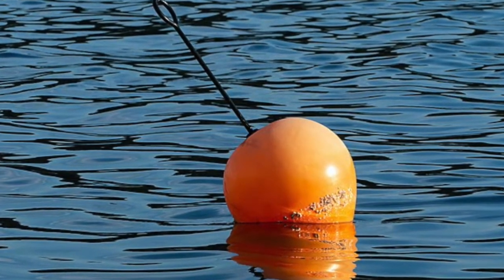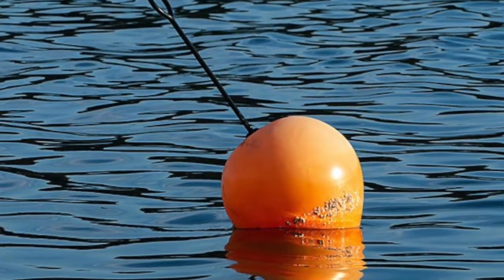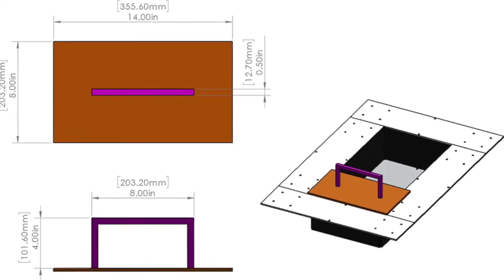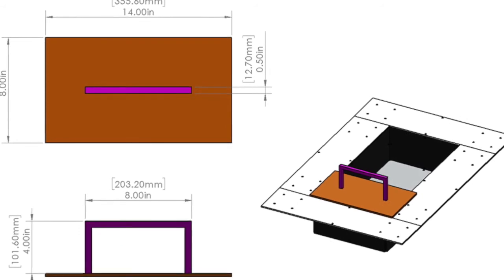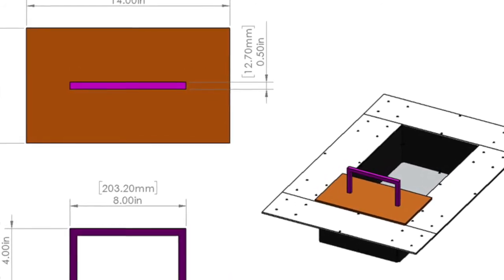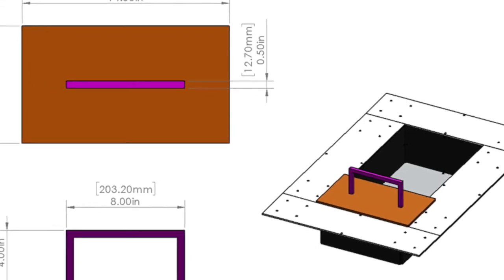It should be no problem to bump the buoys with our control system, so 5 out of 5 confidence score there. The bins task is slightly more difficult. We're concerned about drift in our controls algorithm when positioning our robot over the bin. Regardless, we still have a confidence score of 4 out of 5. With some PID tuning on site, we should be fine.